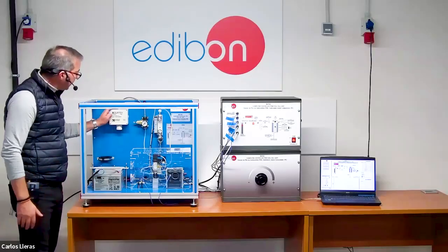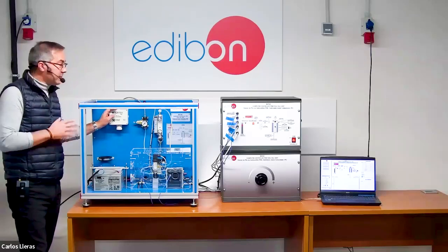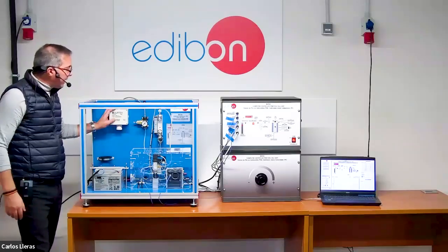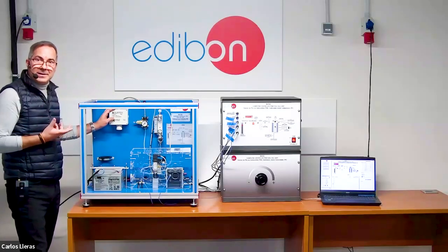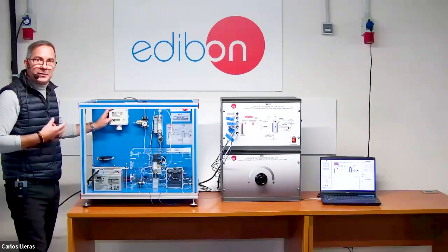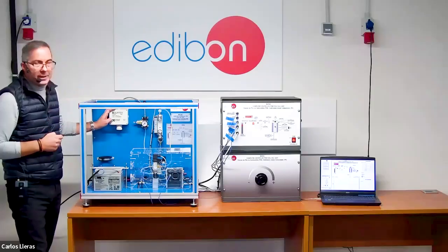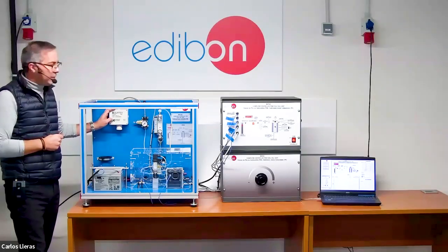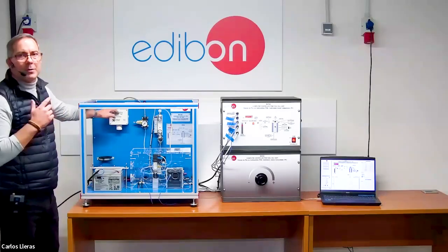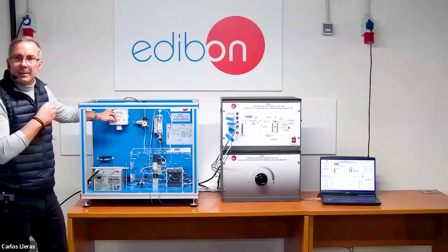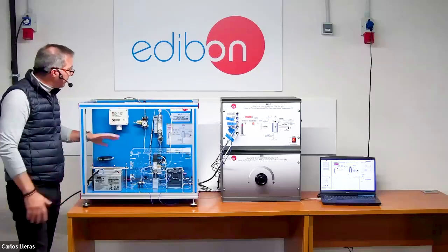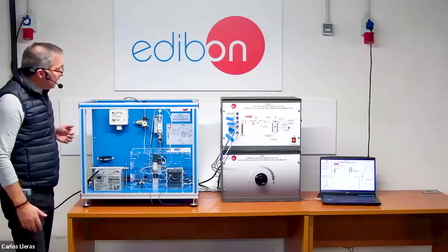Our system also has, for safety reasons, remember these units are meant for laboratories and for teaching, a safety hydrogen sensor emergency device that works like an alarm. It is a gas detector. It will give us a sound alarm, and we can also see that information on the SCADA software. If something goes wrong, if there's a leak of gas somehow in the system, it can be detected, and the valves can be properly shut to make sure that everything is working in safe conditions.